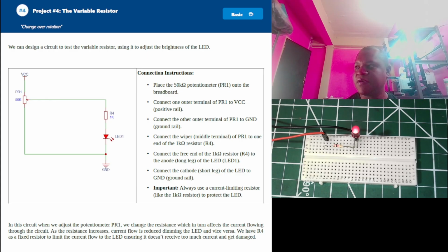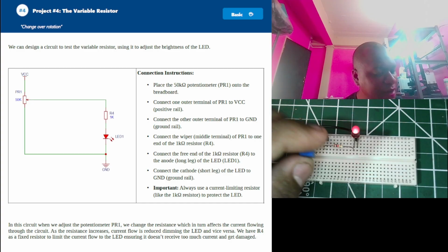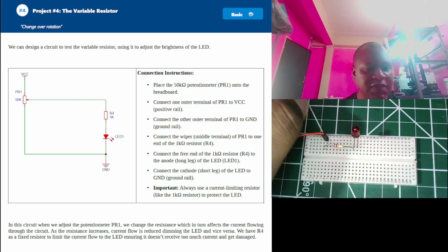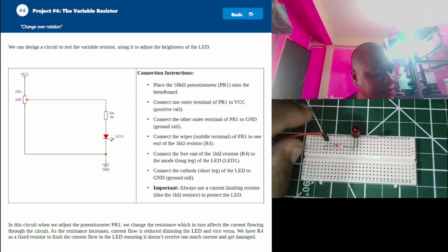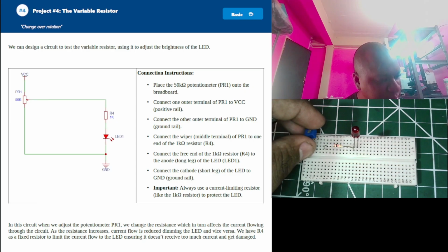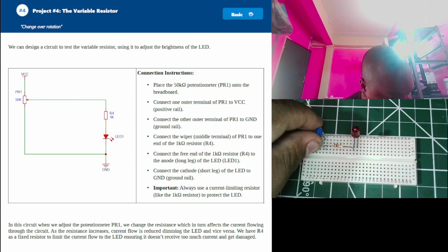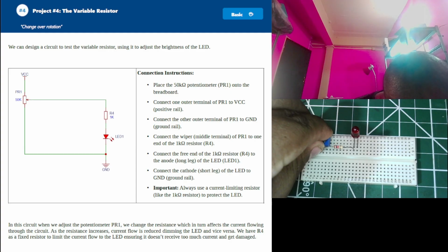So what you could do is, I have a potentiometer here. This is a 50K trim pot, and we'll use that to adjust the circuit. So let's disconnect ground, just as the circuit has. We must leave the 1K with the LED. That's important, right? If you notice how it's set up, this center connection here is the point at which we have the LED now. So we'll put that at the center point here, right?